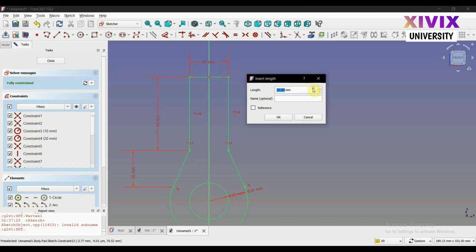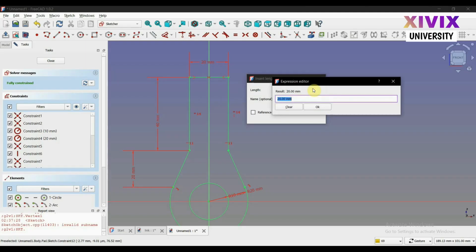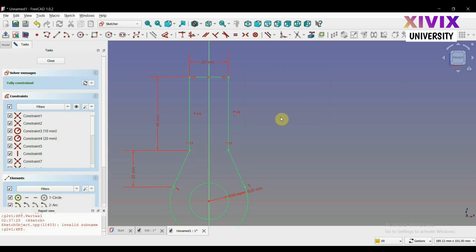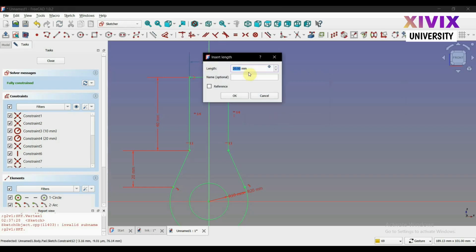Over here you can see this little icon. You click on it to open the expressions editor. You search for constraints and you can see it automatically shows the constraint that we defined. And you can see the result above it shows 40 millimeters, which is the current length of the driver. You can basically use any mathematical expressions you want. I'm going to use the multiplication and 0.5 because I need this line to be half the size of what the main driver, the master line, is.